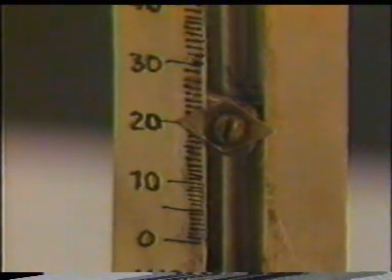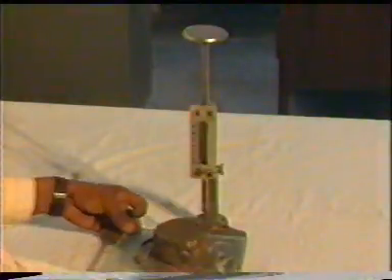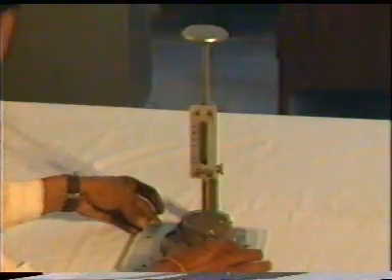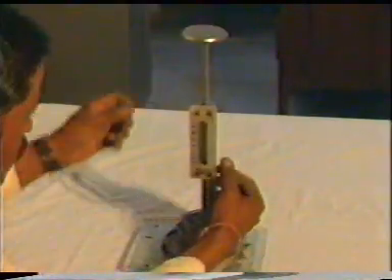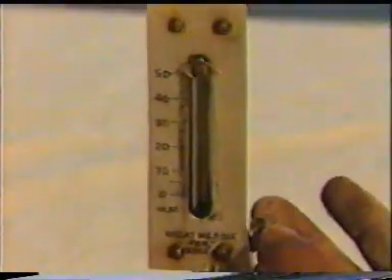In case a reading from the bottom is more than 5 to 7 millimeters, increase the water content. If a reading is less, reduce the water content.